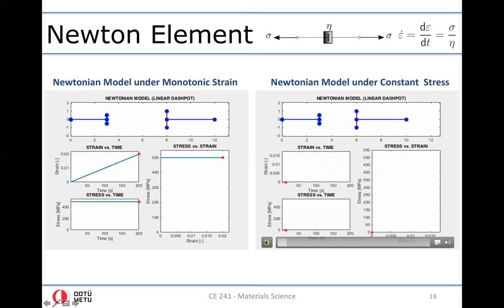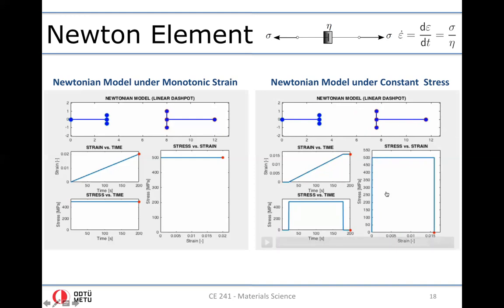Let's play again. We activate, the dashpot opens, and then when we unload, observe the dashpot essentially remains where it was. This deformation remains as a permanent deformation in this particular model. So you see the key difference between the elasticity and viscosity.